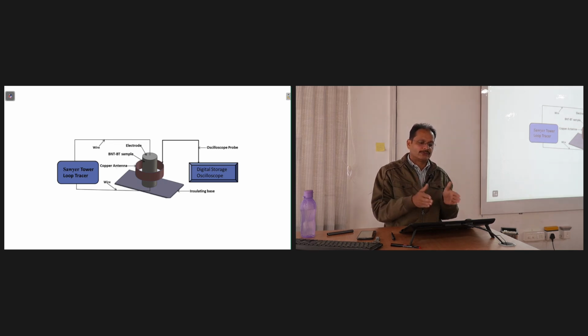In ferroelectric materials, ferroelectricity arises because of dipole formation within the unit cell. The unit cell is not uniform, there is some deviation. So it is referred to as a non-centrosymmetric structure, because the symmetrical position at the center is lost and some variation occurs. Barium and titanium, or titanium and oxygen atoms, are shifted.